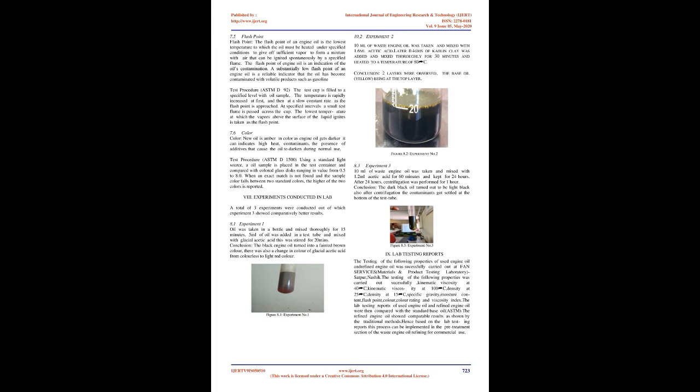Test procedure: ASTM D1298. The sample is brought to the prescribed temperature, standard reference temperature of 15°C, and transferred to a cylinder at approximately the same temperature. The appropriate hydrometer is lowered into the sample and allowed to settle. After temperature equilibrium has been reached, the hydrometer scale is read, and the temperature of the sample is noted. If necessary, the cylinder and its contents may be placed in a constant temperature bath to avoid excessive temperature variation during the test.